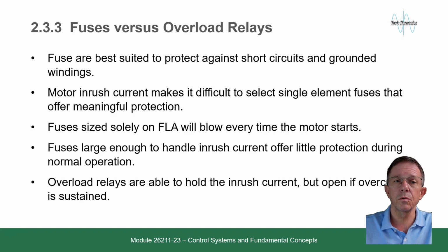Fuses versus overload relays. Fuses are best suited to protect against short circuits and grounded windings. Motor inrush current makes it difficult to select single element fuses that offer meaningful protection. Fuses sized solely on FLA will blow every time the motor starts. Fuses large enough to handle inrush current offer little protection during normal operation. Overload relays are able to hold the inrush current but open if movement is sustained.